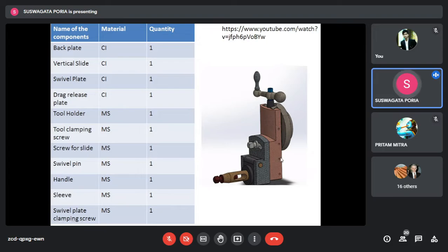And this brownish round plate, this screw, this nut, and this handle are another part of the shaper tool head. So we can divide the shaper tool head into two parts. One part is the clapper box, and another part is the main body of the shaper tool head.